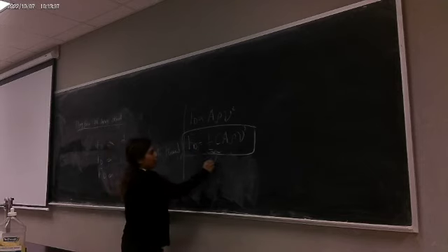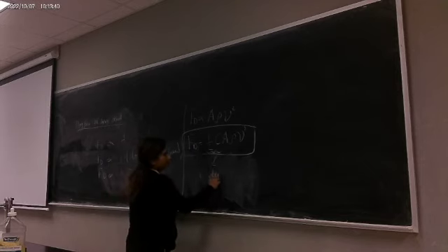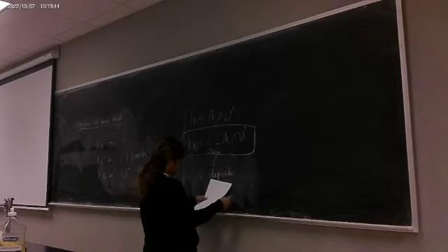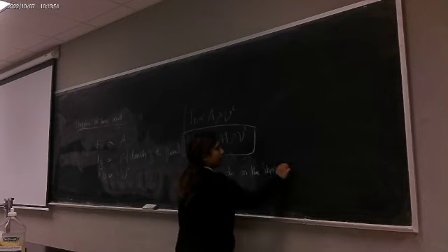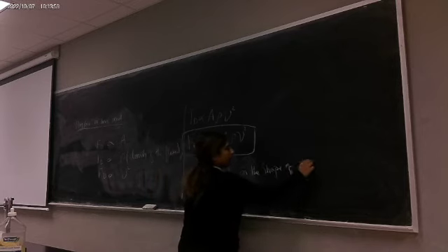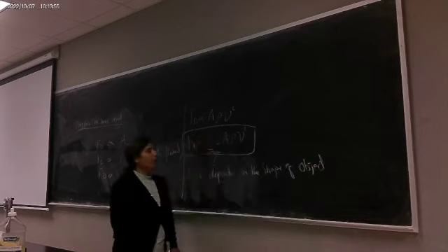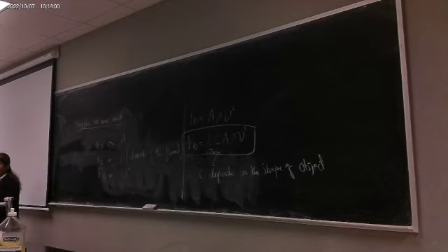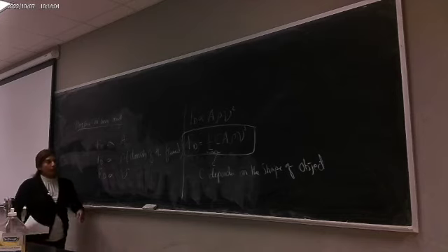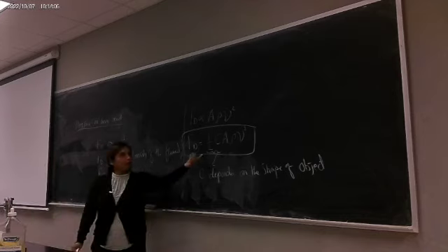And this C depends on the shape of the object. This also comes from the experimental values, using different shapes. That is why the plane should look the way it looks, because based on its shape, the drag force will vary.